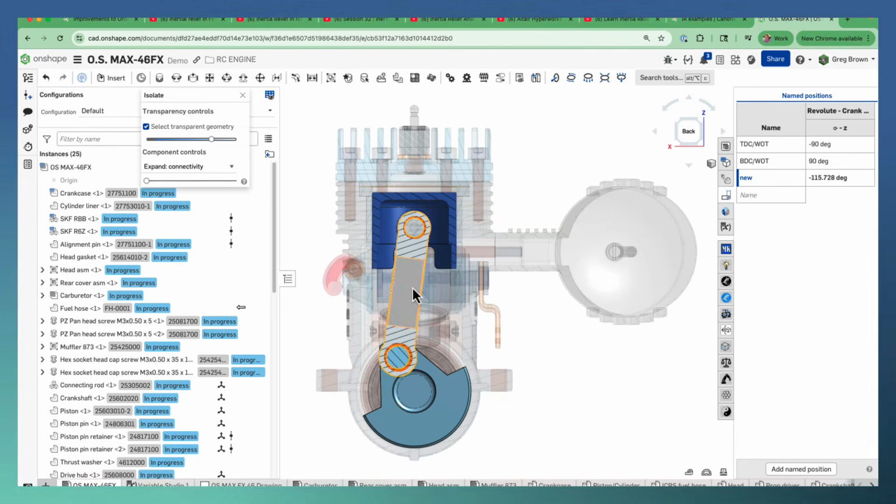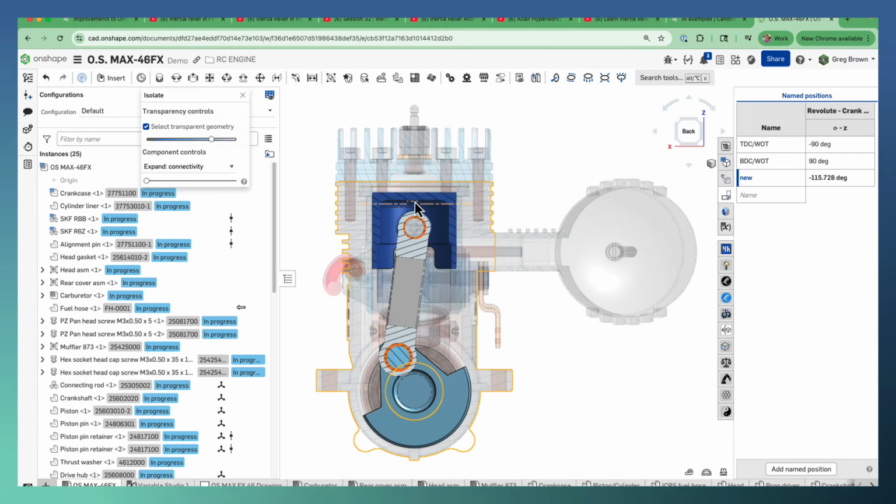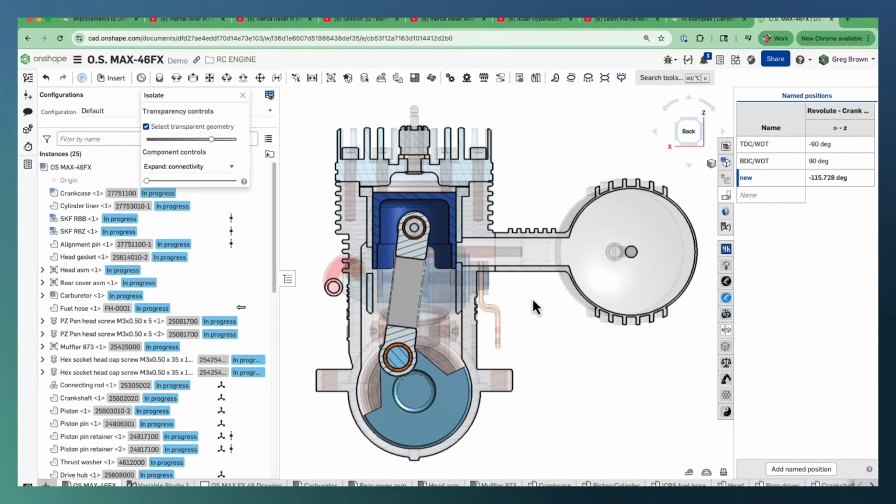So we've got the piston, the conrod, and the crank turning around. Now, at any point in time, there is a force being put onto the conrod by the piston because it's getting the explosion ahead of it up top here, and then there's also a reaction force imparted on the conrod by the crankshaft as it spins. So you think about there's two reaction forces imparting on this conrod, and at any one particular time they're not equal and opposite.